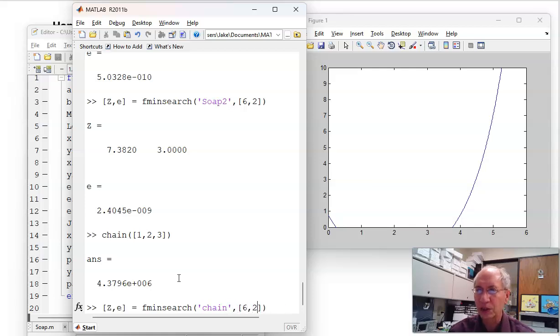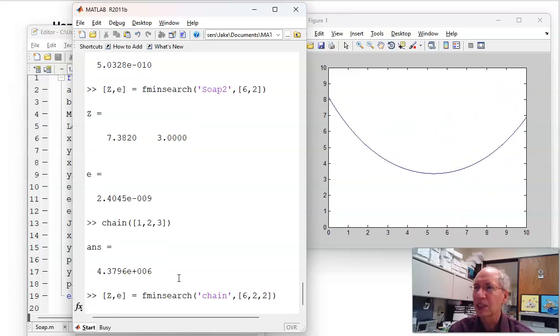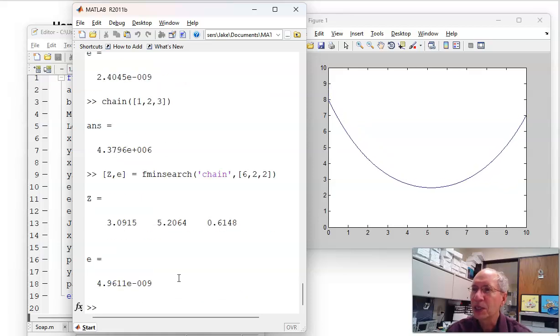So again, in MATLAB, I could guess A, B, M as 1, 2, 3. There's the shape, there's the sum squared error, saying nope, not even close. Or I can use fminsearch. It'll sit there and iterate, and when it finds the shape, it kicks out the answer. Here's A, B, M. There's the shape of the hanging chain with a length of 15.